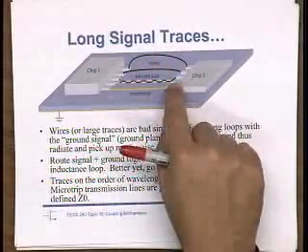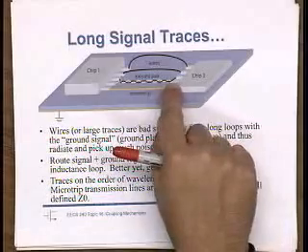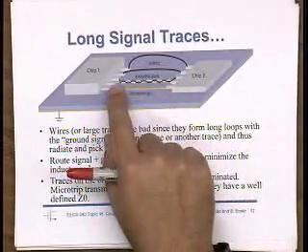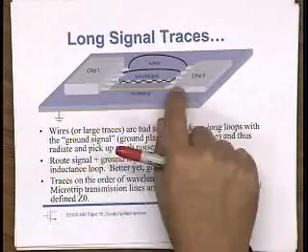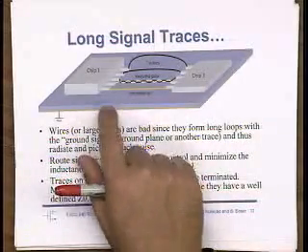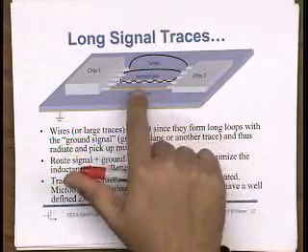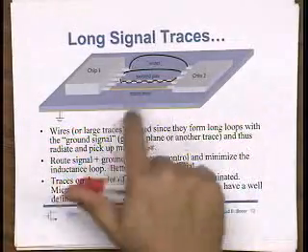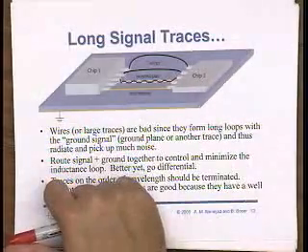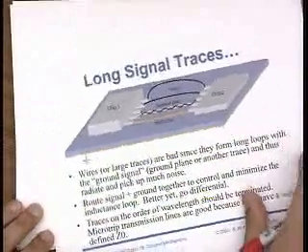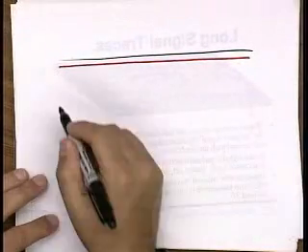So one way to reduce the inductance is through a structure like a twisted pair. And as you know, twisted pairs are very popular for long-range communication. We use them in phones, and for data communication. Why is a twisted pair so much better than just two wires next to each other? So I could take wire 1 and wire 2 and put them relatively close together, or I can do this twisted pair thing.